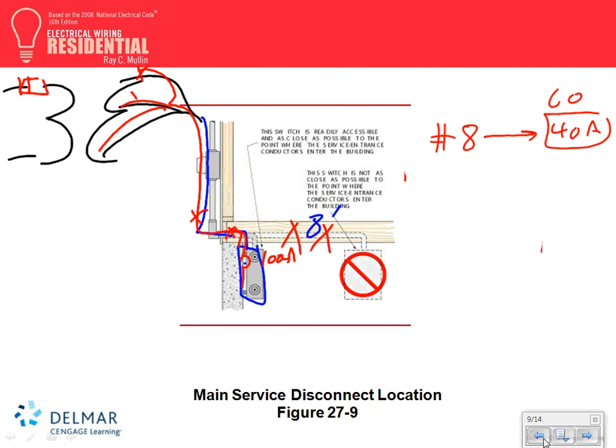Now, I know it's not going to be used in 100. If you look at the 1 circuit and 2 circuits, the service disconnecting means shall have a rating of not less than 30 amps. I'm just trying to defend them. What if you have a service of 30 amp? You can have this special 2 circuit service of 30 amp because of a voltage drop condition. If you have a 30 amp, the minimum conductor that you can use on it is what? Number 8. Even though you could have gotten away with what? Number 10.